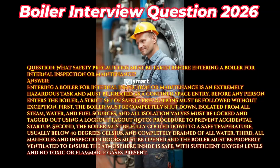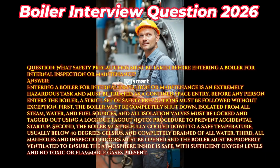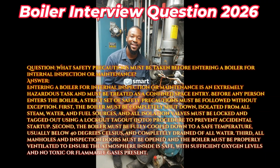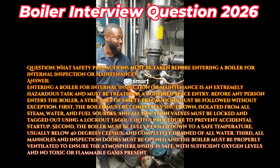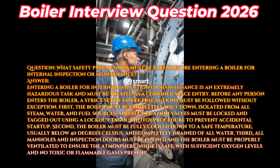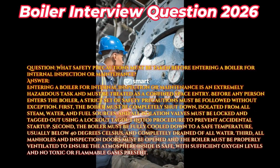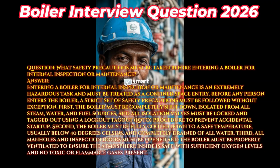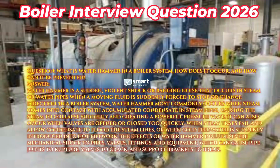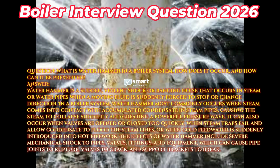Second, the boiler must be fully cooled down to a safe temperature, usually below 40 degrees Celsius, and completely drained of all water. Third, all manholes and inspection doors must be opened and the boiler must be properly ventilated to ensure the atmosphere inside is safe, with sufficient oxygen levels and no toxic or flammable gases present. Question: what is water hammer in a boiler system? How does it occur? And how can it be prevented?